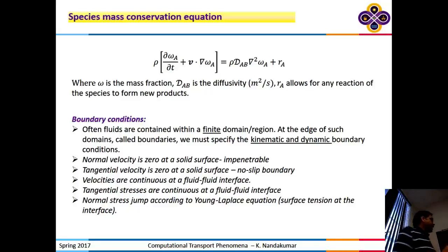Now let's relax this assumption of no slip and put in a slip condition. So the velocity profile actually looks like this, meaning that there is a slip velocity here. And you have to write a boundary condition for that. The no slip condition is u equal to 0. The slip condition is something like mu times du/dr is equal to beta times u. So beta is called a slip coefficient. This is a model that is proposed for fluids that have a finite slip. You take this model and solve that, and you get a profile like that.